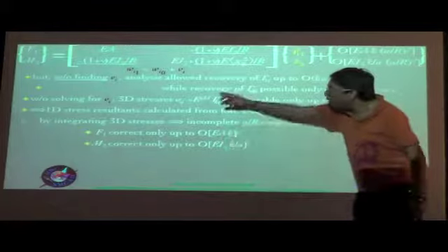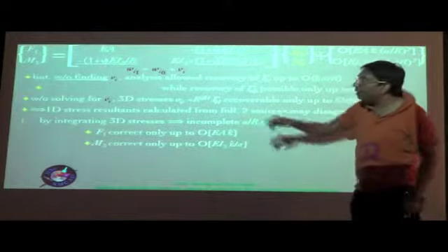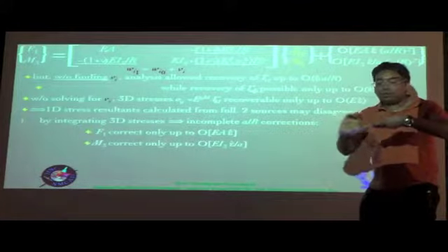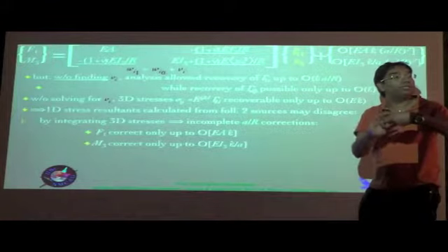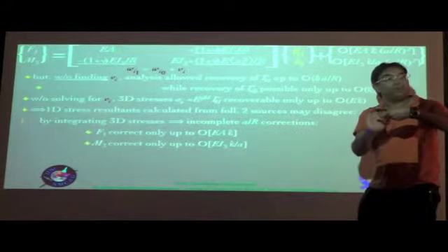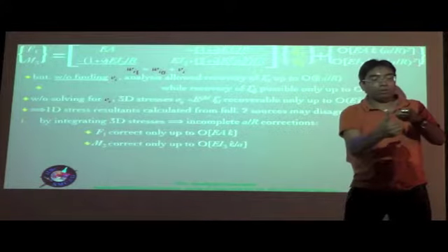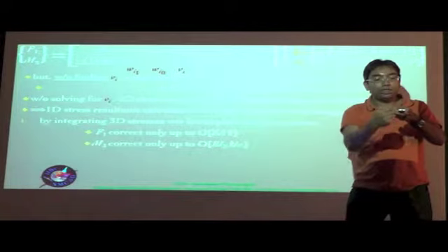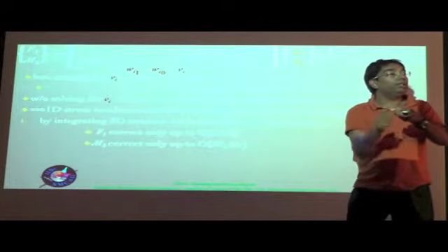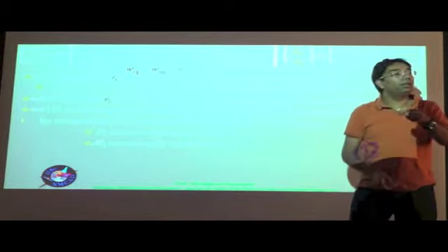Here, if you had determined that instead by using the 3D stresses and integrating it by multiplying, see, M3 is basically the moment about the 3 direction, which basically means that this is the thickness direction. So in the case of a strip-like configuration, the M3 moment would basically be like this. So you're talking about sigma 1 into x2, and then integrating that over dA, which is dx2 dx3 in this cross section, and that's how you're basically determining it.